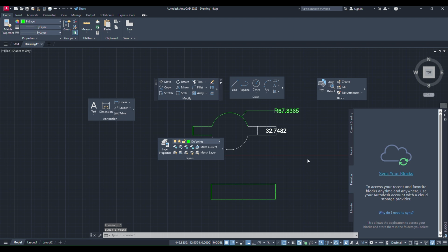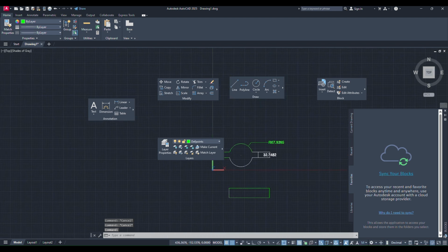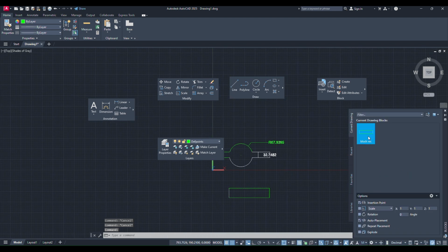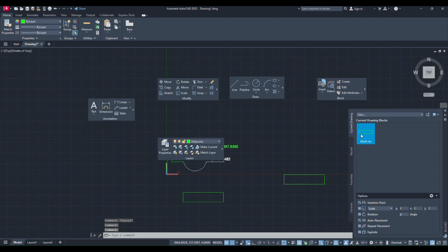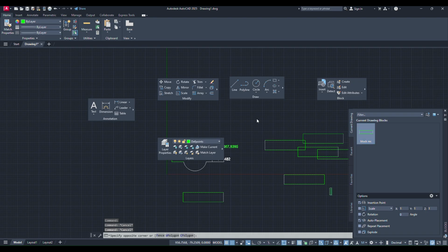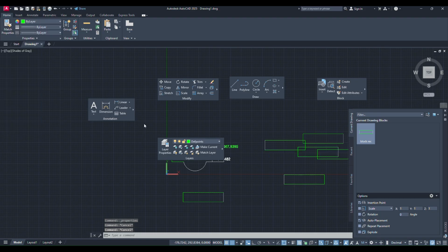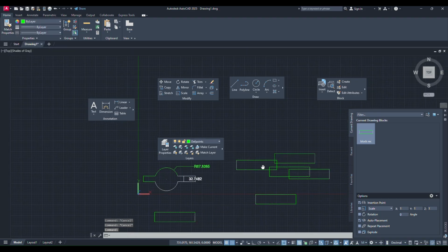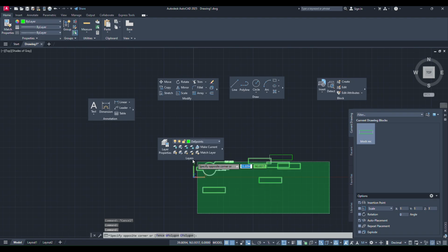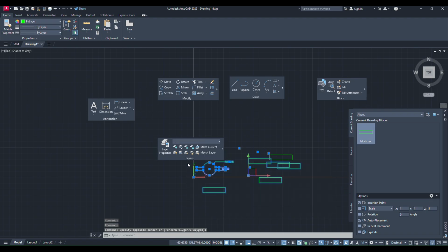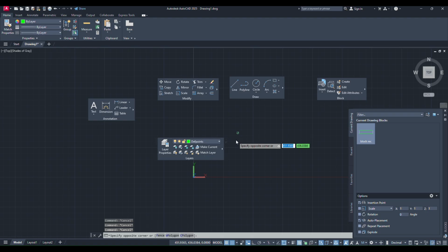Now you will have the current drawing template ready so that you can choose multiple blocks and then count them. How many are there? The current block reference count is 5. It will help you create a bill of material, and then lastly you can see how to print it.